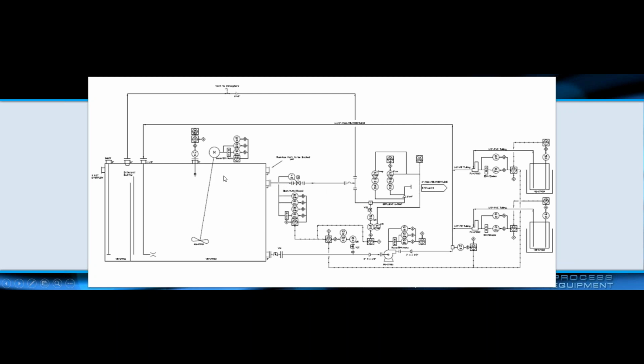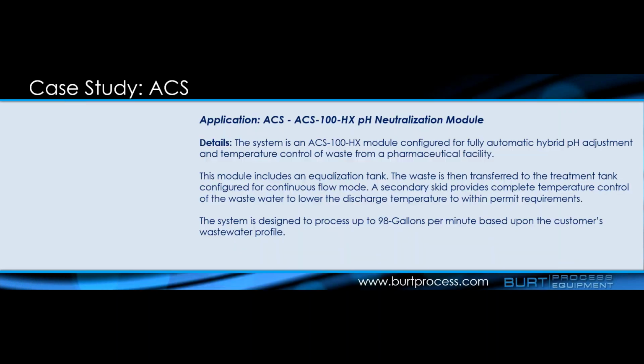When the waste in this treatment tank is not in specification, and again, this is still a CSTR reactor, this valve will close and you'll be able to rise in water level to a higher level. This high level switch is set at that point, so you'll know from an alarm standpoint when you do get to the high level overflow as part of your ACS system. Your circulation loop, you have your pH probes, flow switch to protect. You never want to be injecting chemistry if you don't actually have flow in your system, which is why the flow switch is here. Then your acid and base reagents come back in, educting into your mixer backwash here. There are a lot of options that go into systems: 2-stage, multi-equalization tanks, effluent transfer, but this is your basic ACS P&ID.